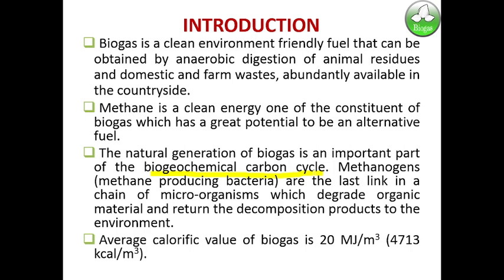Second is called gas handling. When the gas is produced, you need a separate unit to take out the gas from the digester tank and store it in a particular unit. You can use this biogas for cooking, for lighting, and for producing electricity. Anything can be used. The gas can be either stored or used directly. This is a typical anaerobic digestion process, or biogas process.